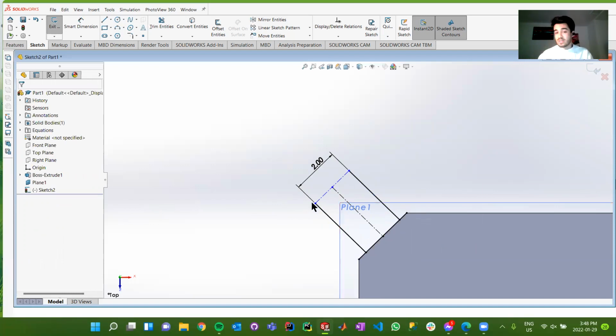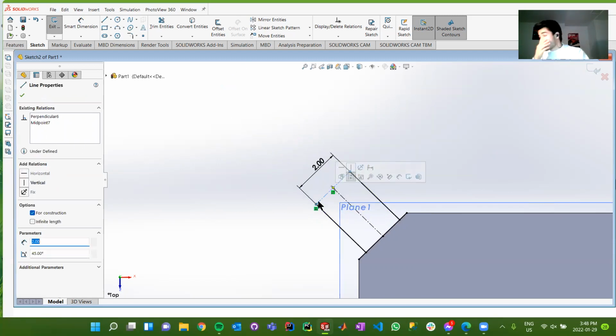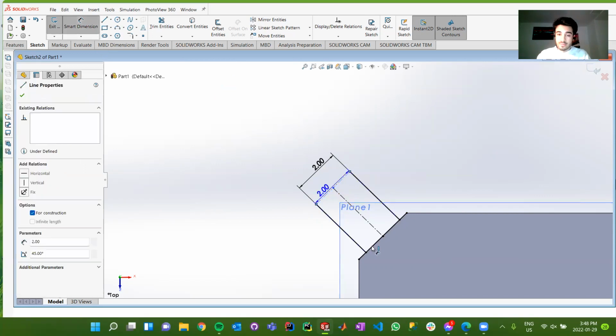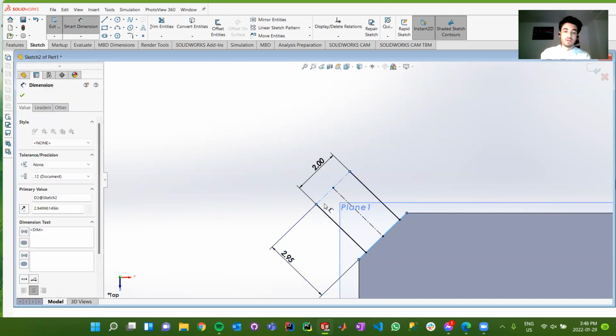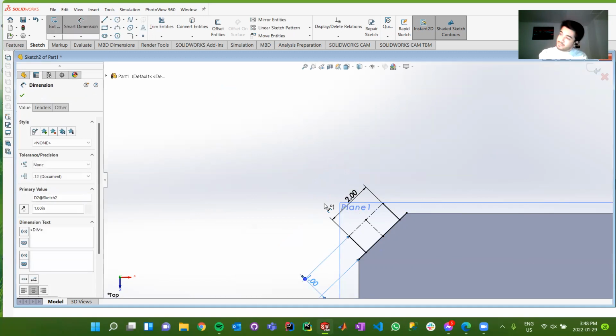We know it's supposed to be in the middle of this base with the following constraints that we've attached to it. Now, the reason why this top face is blue still is because of the fact that we don't know how long this bracket should be, right? I can still freely move this around. So let's attribute a length to that. In terms of the CAD that I already created before, I believe that is 1 inch away from our base. So I'll click here, I'll click on the base, and we'll enter 1 as the length of our base. Does that look right? Yeah, it does.